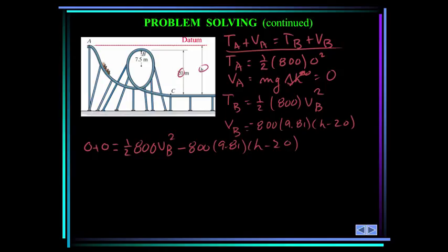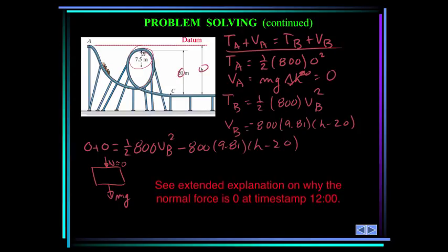So now I have one equation and two unknowns, so we need to go to kinematics to get another equation. To do that, let's find the velocity at B so that it doesn't leave the track. Let's draw a free body diagram. So we have the weight, mg, and the normal force from the track. Now it's important to note here that the normal force is going to be 0. We're looking for the minimum height required, so as the car moves around the track, it's just going to reach the top where the normal force is 0, and then it's going to drop again.